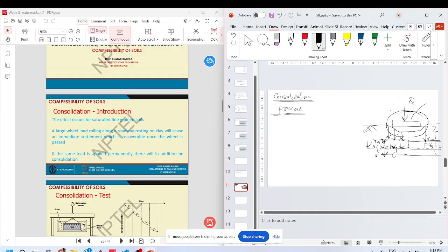So basically, when you are putting in a load from the top and overburden over this layer, it is effectively getting consolidated. It was at an equilibrium. It would not settle on its own. The particle stresses were rearranged in a way that everything was in equilibrium.